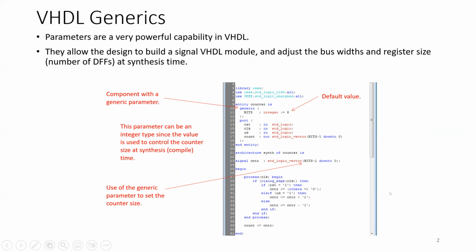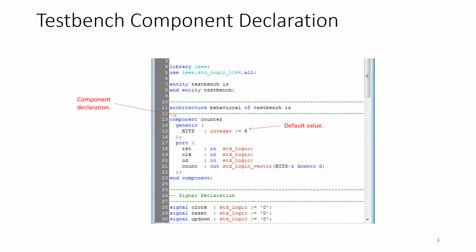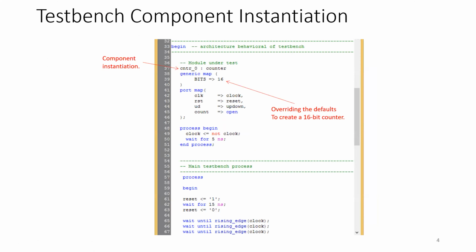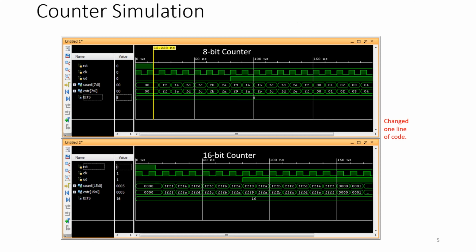So you know what is meant by generic, this statement, where I can specify these bits. I specified as integer of 8, and then if I want to make this program, which is a counter, 16-bit, 32 bits, I just change it from this point. Isn't it a more efficient way of controlling how many signal paths you have? Yep. Perfect.